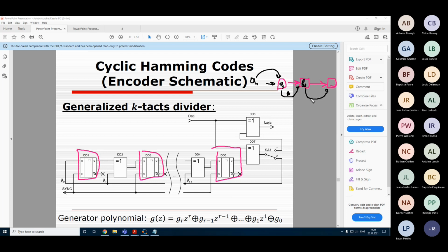The previous value, like B-1, goes to here, and so forth. So basically, each new data recorded into the first flip-flop then shifts out the remaining data in the entire register. So at the output, we'll have B-2. Yes, so this is the classical shift register made from flip-flops.